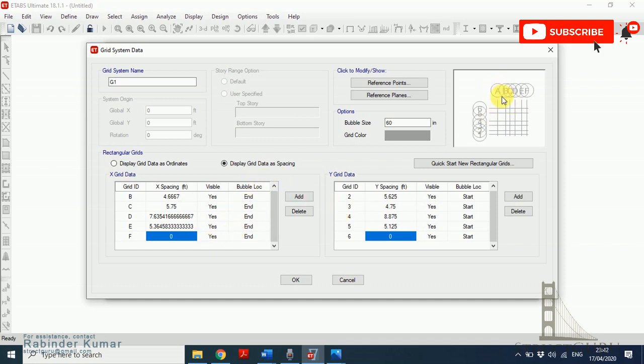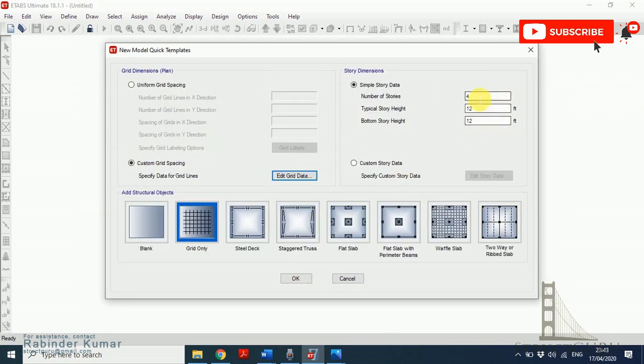As you can see, the bubbles are overlapping. To reduce the size of the bubble, you can insert different values over here. So 60 inch is higher, so start from 20 inches. So 20 inch is fine, and no bubbles are overlapping. So this grid data is added. Click OK. Now we have to go and change the story data.